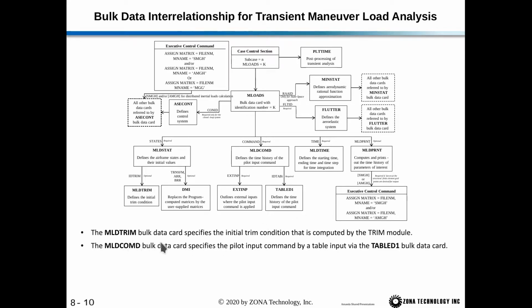So the MLDTRIM card specifies the initial trim condition that's computed by the trim module, and then the MLD command card specifies the pilot input command by a table input via the TABLED1 bulk data card.